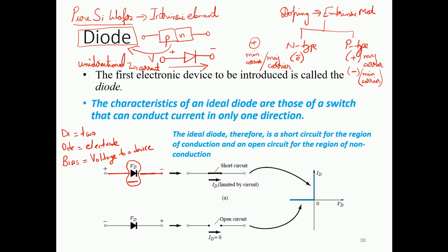Again, keep in mind that our diode will be made with a semiconductor material as discussed in our first lecture. It can be constructed using the semiconductor material silicon. Nowadays it is used with silicon. Earlier, before the purity of silicon or the excavation of silicon, germanium was the choice of material. We can also make a compound if you want to increase the processing speed between elements, and that material will be a combination of gallium and arsenic known as gallium arsenide. This is a compound structure, and these are single crystalline materials, which we discussed in our previous lecture. So now what happens with the functioning of a diode?